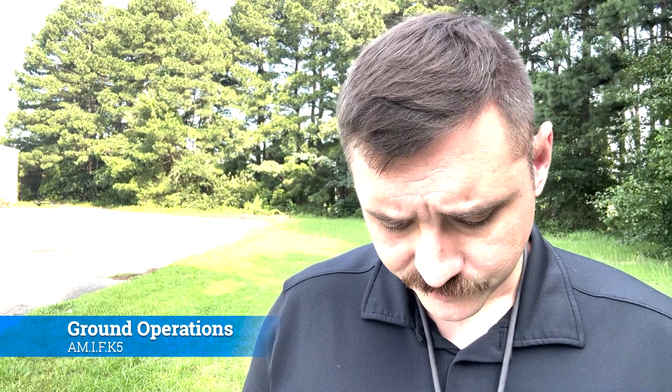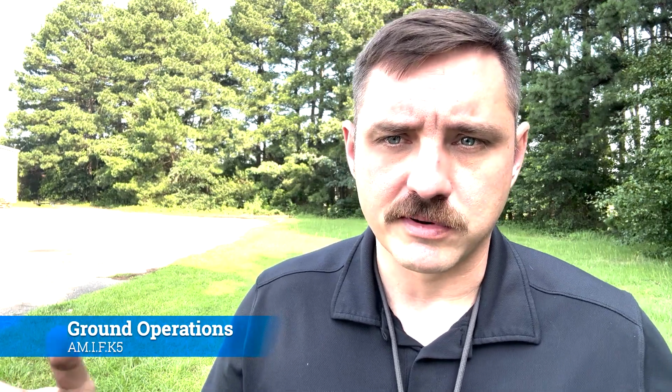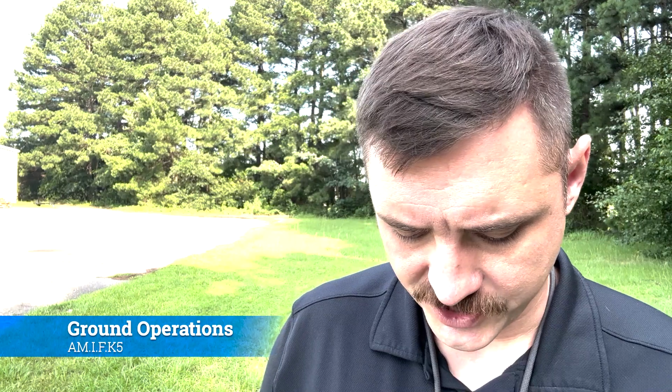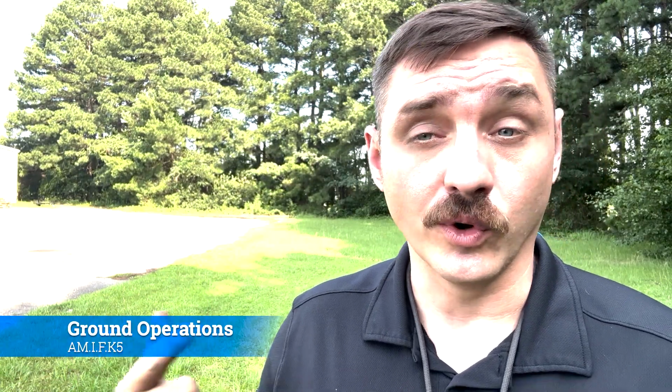All right. After your engine is operating smoothly, move the mixture control to the full rich position if started in the idle cutoff position. Essentially, if you had to put it in idle cutoff and it's just starting, it's going to want to stumble, so go ahead and go full rich if you didn't already do that per the checklist. Then probably the most important thing to do is watch the engine gauges. Some examples could be your fuel gauge, your fuel flow gauge, your suction gauge, your engine temp, and your oil pressure.